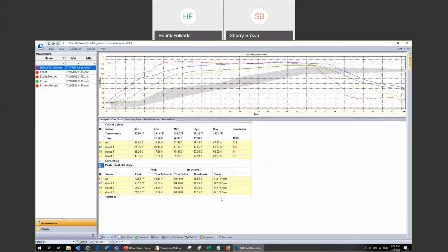When I talked about the maximum amount of time that it could be in the oven at 250 degrees Celsius or 200 degrees Celsius, that's referring to how much time it can spend in there before those heat sinks get overheated. But they can actually be removed from the thermal barrier, meaning you can buy additional heat sinks. So if you want to run continuous tests, you just swap out the heat sinks with a cool one and run another test while the heat sinks are cooling.